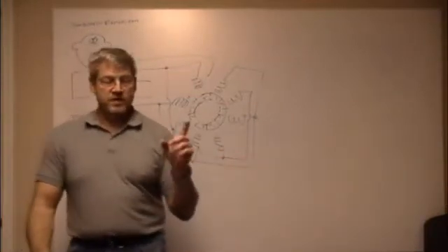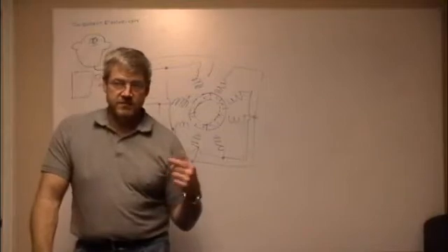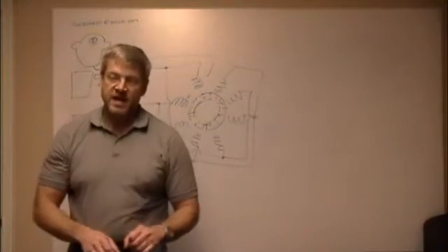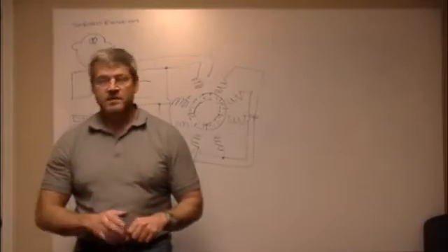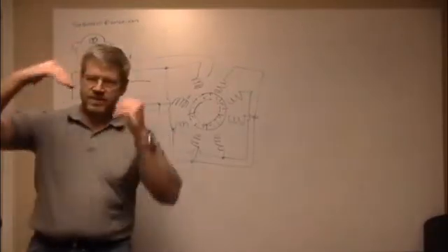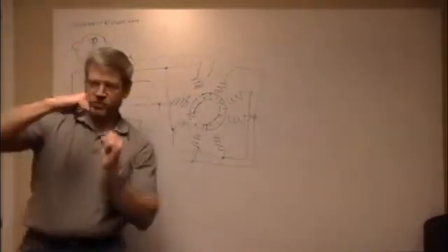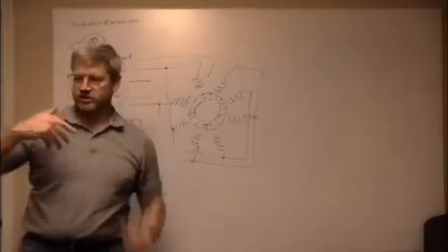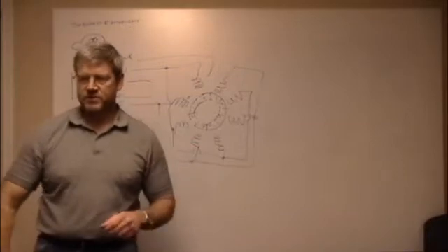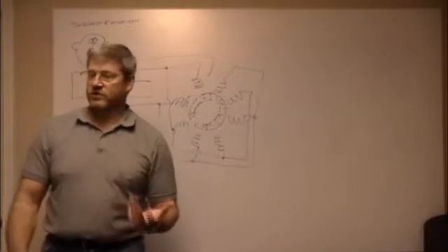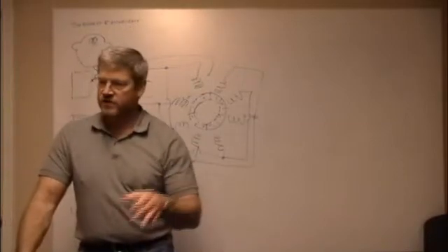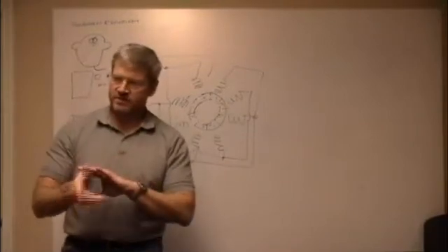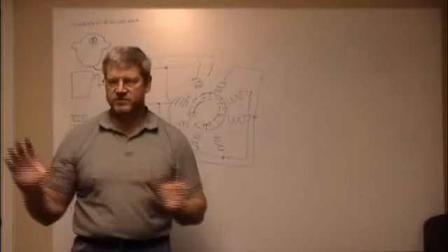One of the drawbacks with a stepper is I have to go through all those steps. And if I go too fast, I'm basically causing the magnetic field to rotate and push it along with it. I can go too quick, and it won't overcome the inertia of the whole system on it. That's why if you look at 3D printers, if you set them up to go too fast, they'll start missing steps. You're moving the field faster than you can move the hardware.